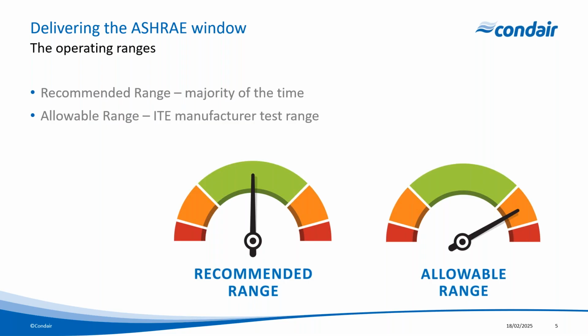So the key takeaway here on this slide is that the IT equipment should operate within the recommended range for the majority of the year, and the allowable ranges were specifically created to allow for potential excursions that are not outside the capability of the IT equipment under extreme load conditions. And then the actual range is where the facility and/or ITE operator decide to operate their equipment. That's really going to be a balance between optimizing efficiency, reducing the total cost of ownership, as well as addressing reliability issues and potentially improving performance.